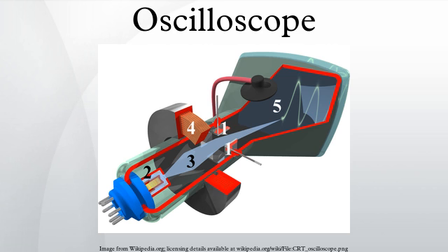There is a variation of the DSO called the digital sampling oscilloscope that can exceed this limit for certain types of signal, such as high-speed communications signals, where the waveform consists of repeating pulses. This type of DSO deliberately samples at a much lower frequency than the Nyquist limit and then uses signal processing to reconstruct a composite view of a typical pulse. A similar technique, with analog rather than digital samples, was used before the digital era in analog sampling oscilloscopes.